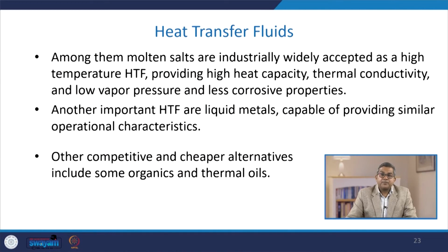Another important heat transfer fluid is the liquid metals, capable of providing similar operational characteristics which we discussed for the molten salts. Other competitive and cheaper alternatives include some organic and thermal oils, and sometimes the synthetic organic ones. We have already discussed various things related to the heat transfer fluids in the CSP section.